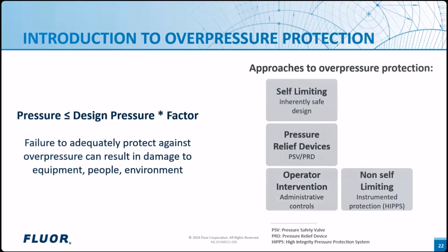If a pressure relief device is not practical, but there is sufficient time for operator intervention and adequate operator training, then credit can be taken for operator intervention to mitigate the event. For example, to close the feed valve to prevent overfill when the liquid reaches a high level.